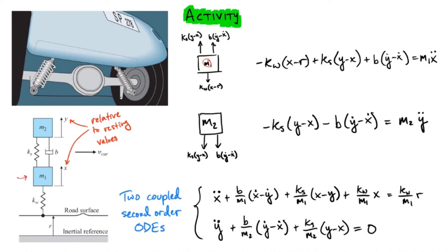And again, the really important thing when you're dealing with these free body diagrams is to make sure you know which direction you're drawing your arrows, be purposeful about that, and then think about what it means for these variables x and y to be positive or negative. The arrow here indicates that y being positive goes up, and this arrow means that x being positive also goes up. What you want to think about is, what are the forces that this block is going to feel when x becomes positive? When x becomes positive, you're going to be stretching this kW spring. So it makes sense that the force would be pulling down. That's the reason I've personally made that choice to put that down, and write the force such that when x is positive, that's a positive force. So now the positive x direction pulls this block down.